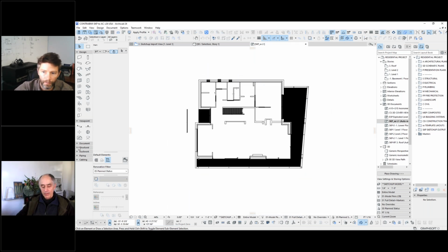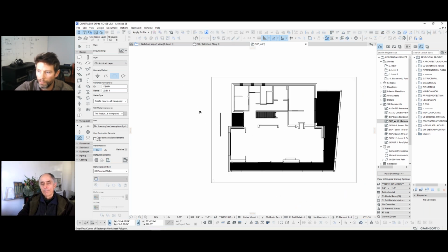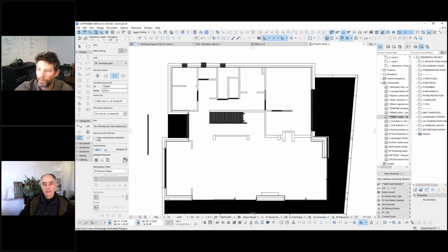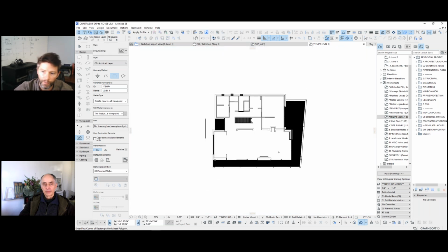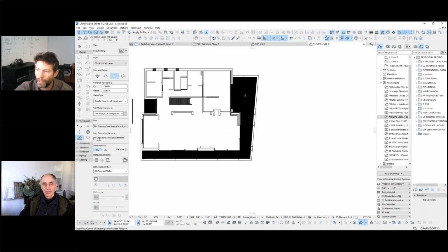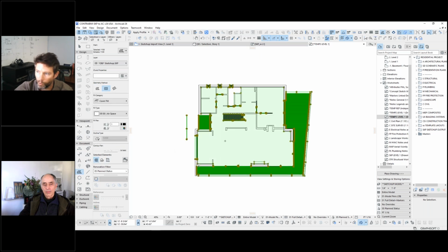And then from here, if we wanted to switch this to line work, we would add a worksheet onto it. And then from this worksheet, we can open with these view settings. This just created a new worksheet for that temp 3. And then now this would ultimately turn into line work. And if we wanted to simplify any of this, we could zoom in and we can see that because it was a projection, there's a lot of little lines and stuff over there on the edge. From this view, we could go through and start stripping things down for the performance of things.